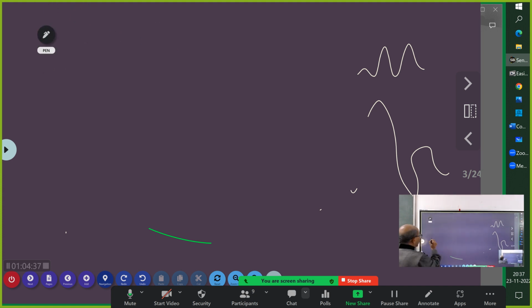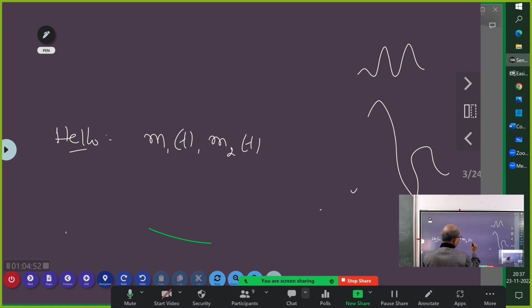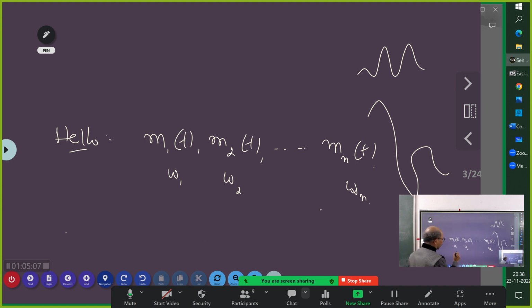So as I told you, this word hello will contain many signals, M1T, M2T and so on. Each one is a sinusoid. Now this frequency is omega 1, this is omega 2, and this is omega n. This can be something like 100 Hertz, and this can be something like around 900 Hertz. That means my hello will contain many frequency components starting from 100 to 900, like 100, 101, 105. So it will be a composition of all this.